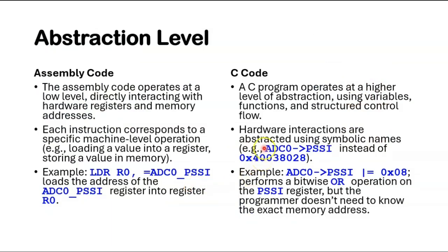The hardware interactions are abstracted using symbolic names like ADC0->PSSI, instead of using 0x40038028. So it uses this instead of this.